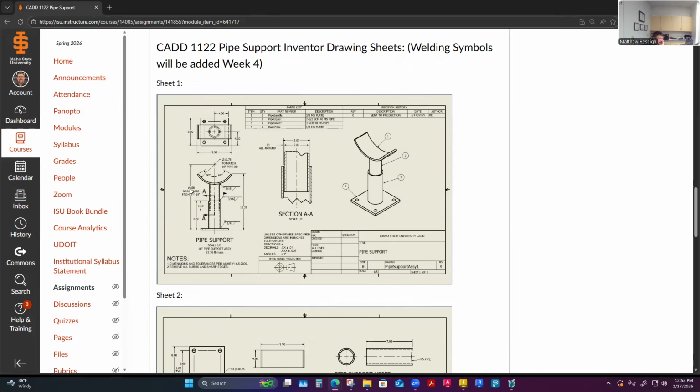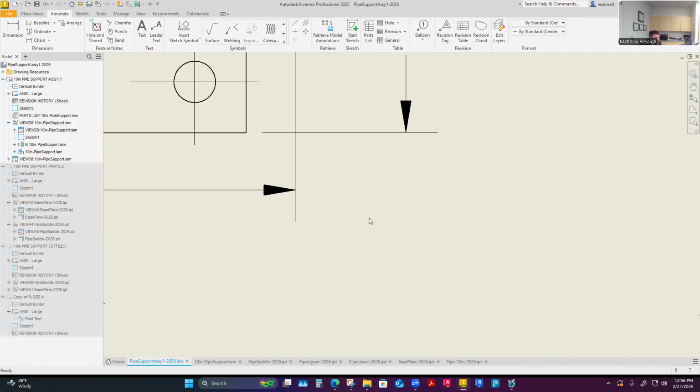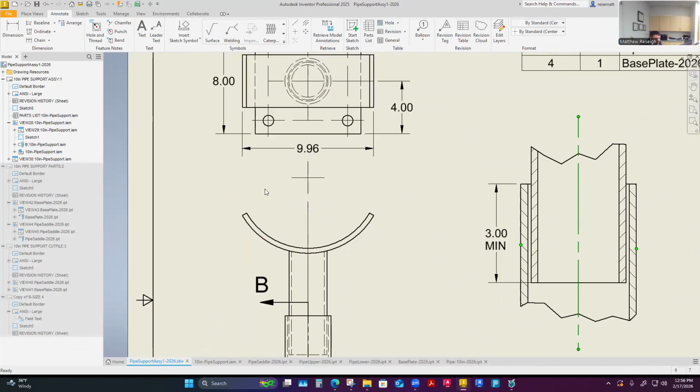I added this dimension, and this was me checking that I was at modeled height at 19, and I just added adjustable from 14 to 19 in my description as part of the text, just like I did with my minimum dimension. So then I've just got some angular dimensions, and this one is just a leader line text. I think this 10 inch is a dimension that I've added, and I know it's a diameter. I'm calling that out because it just matches that much pipe. So this is technically a pull out a radius. The other thing I've showed some people, let's do that one because this one came up on other things and I'll use it on sheet two as well.